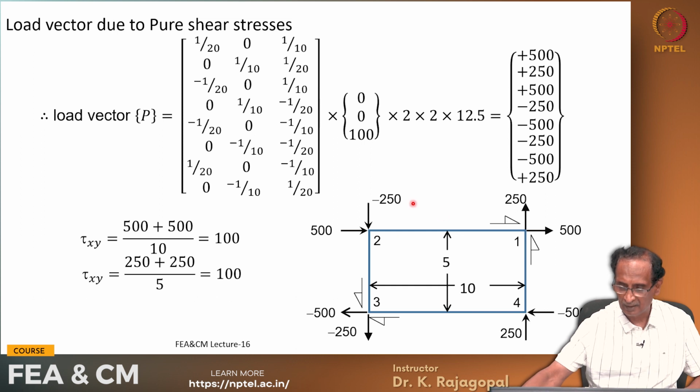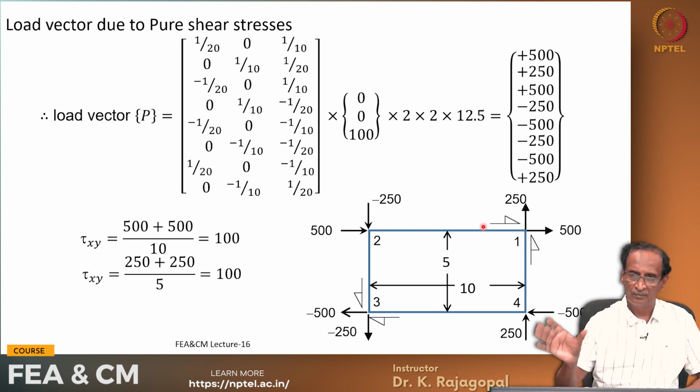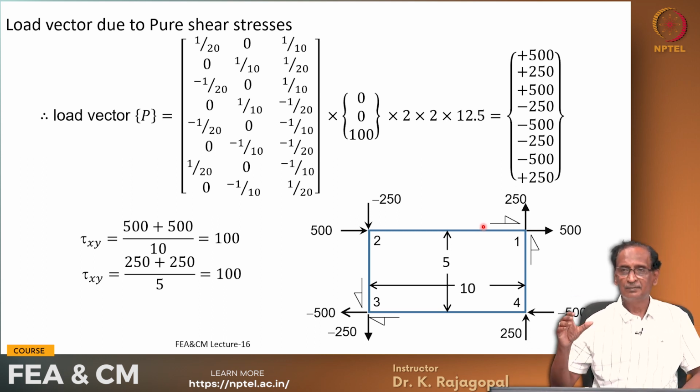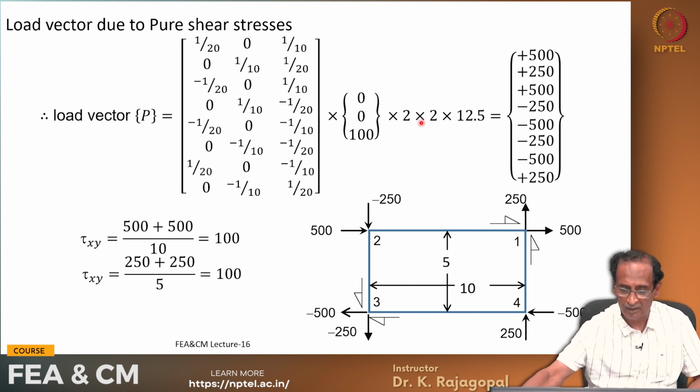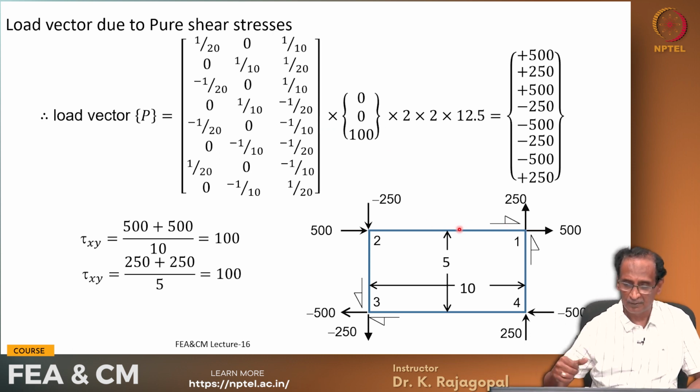And so actually this is our sign convention. So any shear force that develops a clockwise moment around an interior point, we call that a positive shear force, and this is the positive shear stress, positive shear force and positive shear stress. Okay.